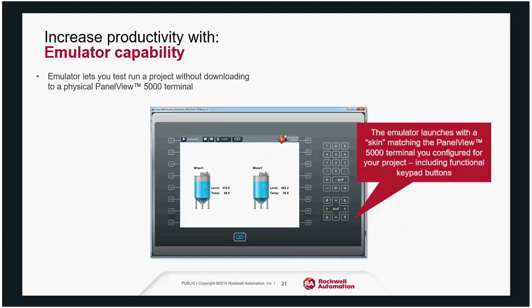The only thing you can't do is data logging, for obvious reasons, since you can't plug a USB or SD card into your emulator. And in the beginning of your View Designer, it will ask you to link your emulator to your controller via Ethernet.